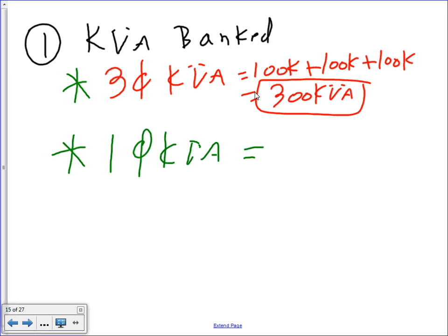Now the single phase kVA. Did you guys see the single phase kVA? The single phase kVA is actually you take the 150 that you did, subtract 50 out of it, subtract 100. Why do you think I subtract 100 out of that? Subtract 100, it's already used somewhere else, and that'll get me 50 kVA.